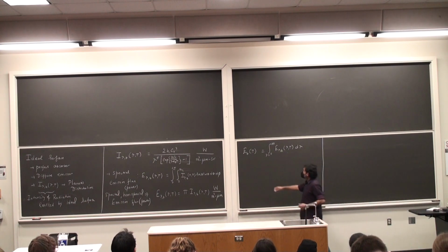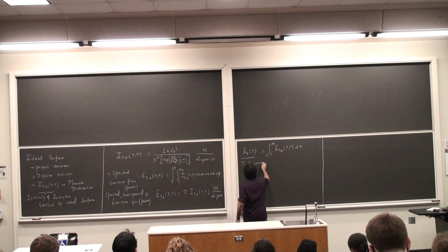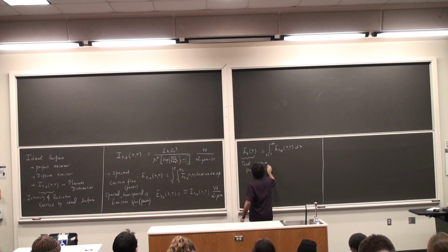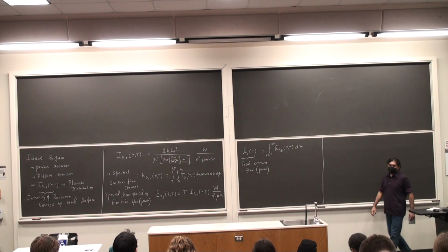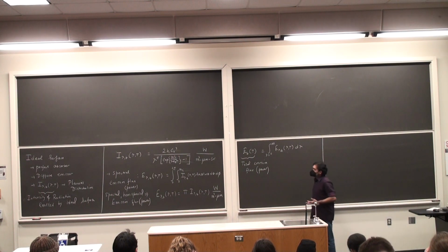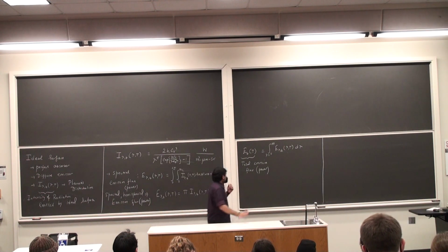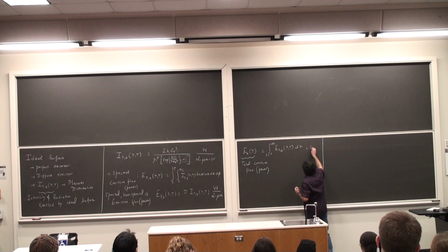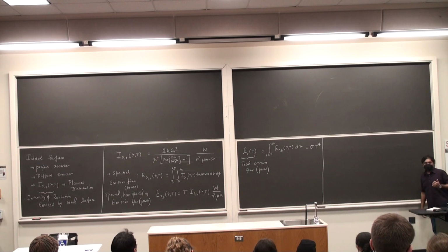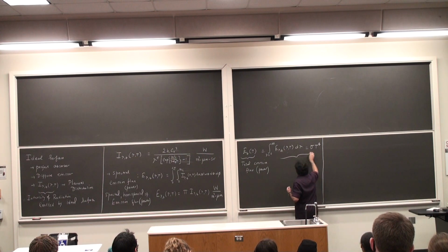This is the total emissive flux or power. Once again, this is a notion of power per unit area, okay? And this integration, if you take the Planck distribution and then multiply it by the factor pi and then you integrate it, you end up getting the Stefan Boltzmann law. So this ends up being equal to sigma T to the power 4, where sigma is something that we've seen in the past, the Stefan Boltzmann constant, okay? So this is the Stefan Boltzmann law.